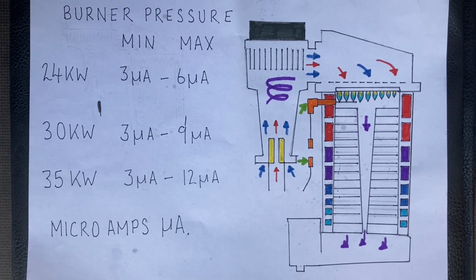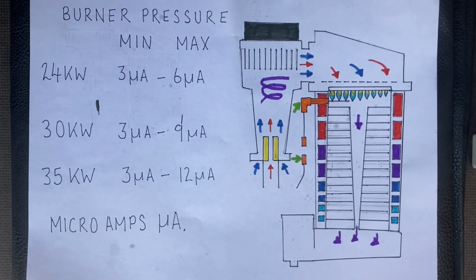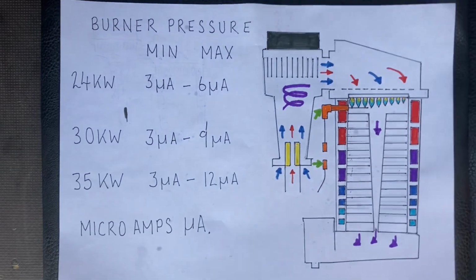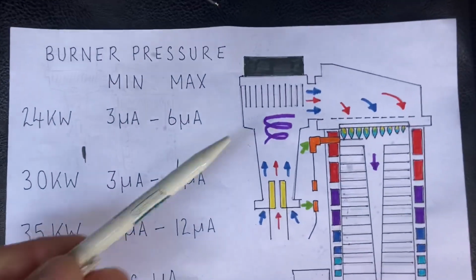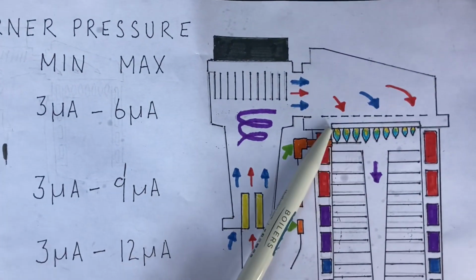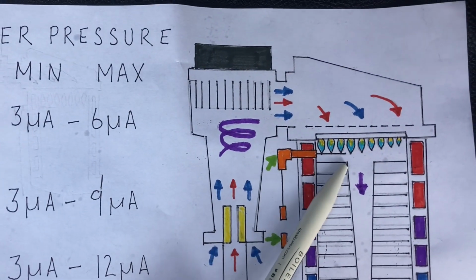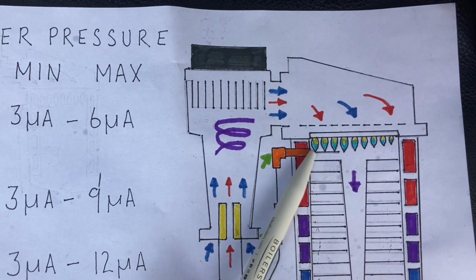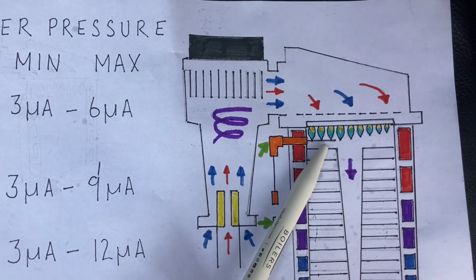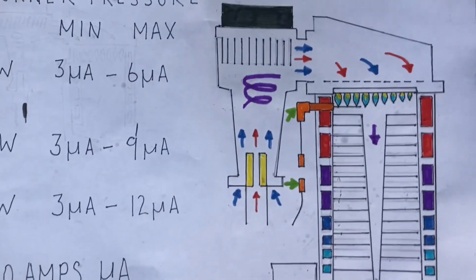Since I've worked it out, I've applied the principle, and obviously you need a clean probe. So before you do this, make sure you change the probe, or that there's no carbon on the probe. I've done a video on how to test this.